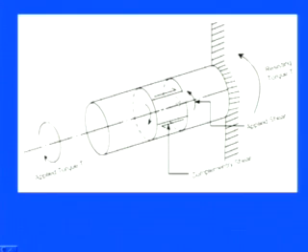If you see the notations, this one has a tendency to move the object in a clockwise direction, and this one has a tendency to move in the opposite direction. If the shear stress and complementary shear stress are exactly opposite and equal, then only can we say that the bar is in exact equilibrium, maintaining equilibrium under the application of these four combinations. You see, they are acting in this particular opposite direction, and they are opposite in this direction.